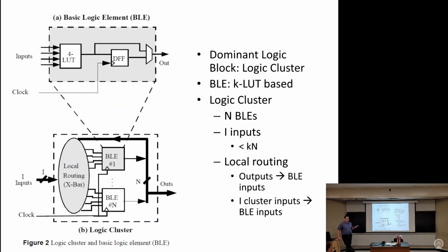So you'll see that, if I get to the end of this lecture, in the latest architectures from Altera and Xilinx, they're diverging a little bit. So you could argue that they're starting to move towards 2 levels of hierarchy instead of 1, or maybe 1.5 levels of hierarchy instead of 1. But yeah, for big FPGAs, nobody does a lot of levels of hierarchy.